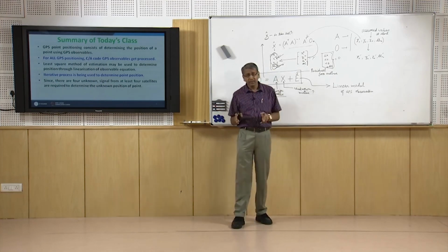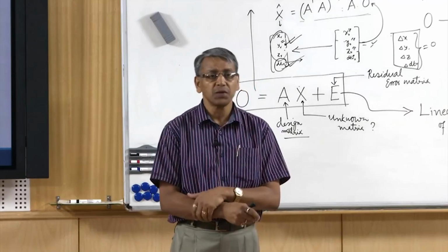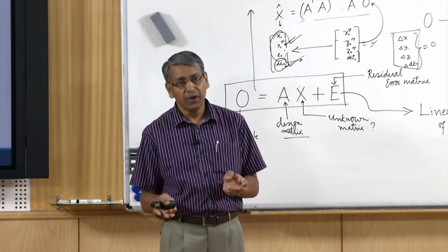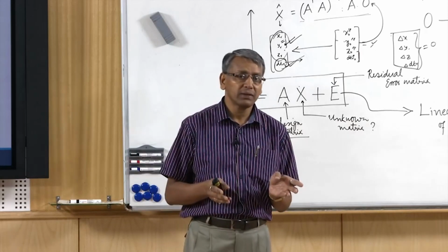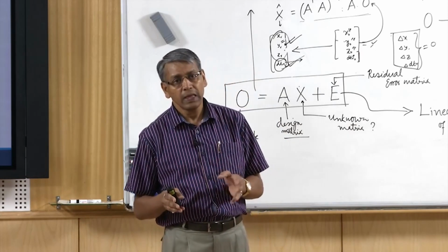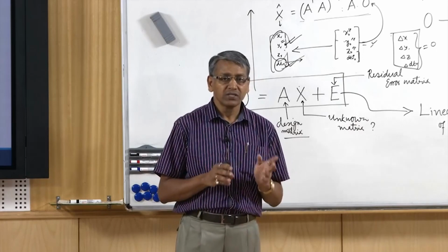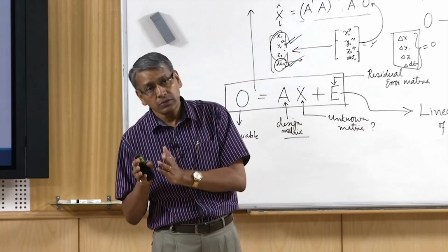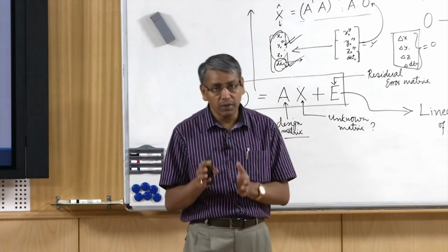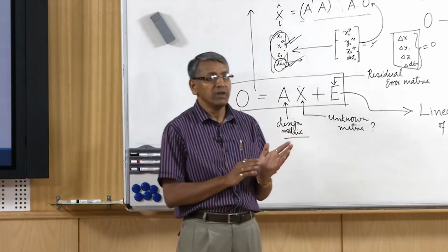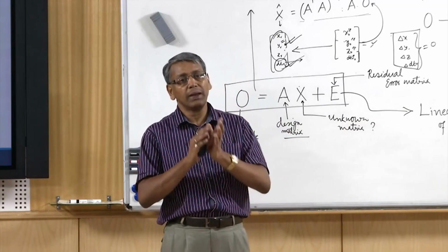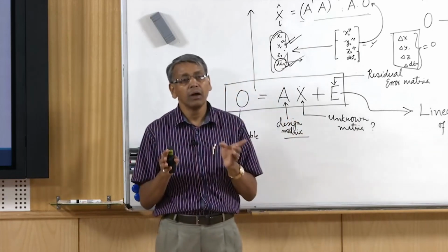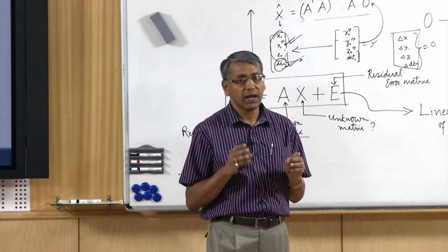There are many methods by which we process the GPS data to find out the position of the receiver. One of the methods is least square analysis, in which we first have to linearize the nonlinear GPS pseudorange observable, then after linearization we have to develop the linear model, and that model will be solved by making use of least square analysis.